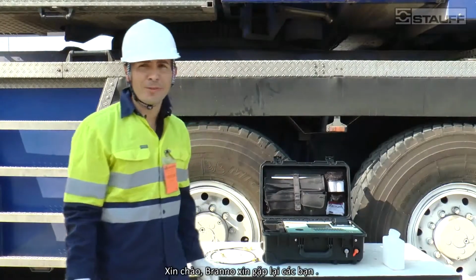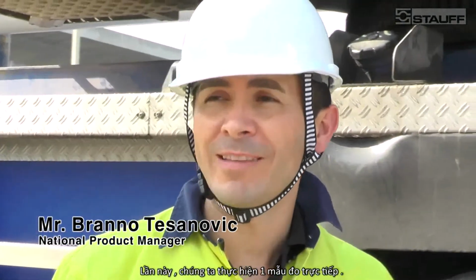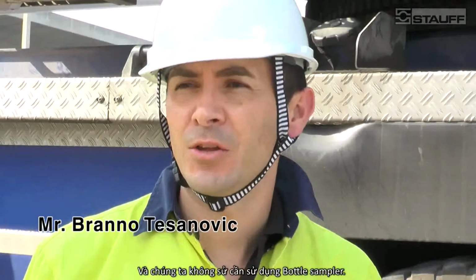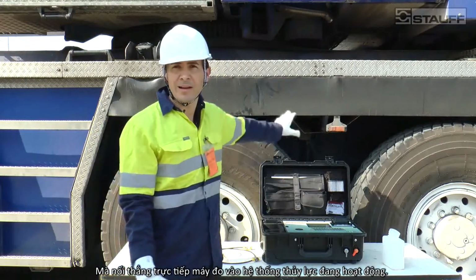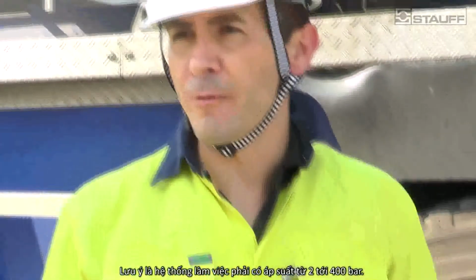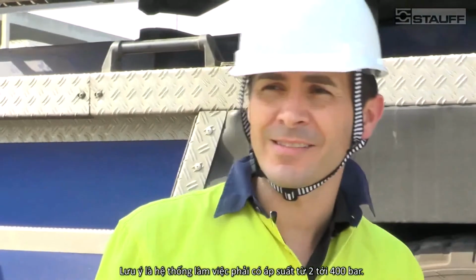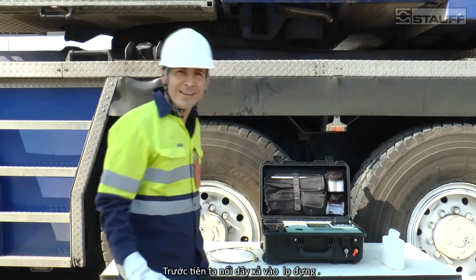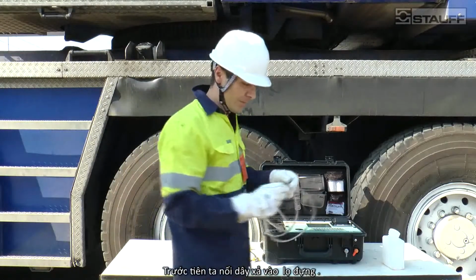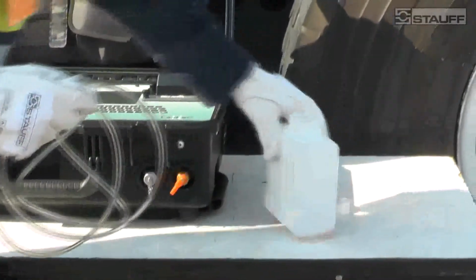Yeah, hi, it's Breno from Stauff Corporation again. This time we're going to perform an online test. So in this case, the bottle sample is not required. We can connect our particle counter directly to the system. Just ensure before you connect that you have no more than 400 bar of pressure in the system or no less than 2 bar. So the first thing is to connect the waste hose into the waste bottle.